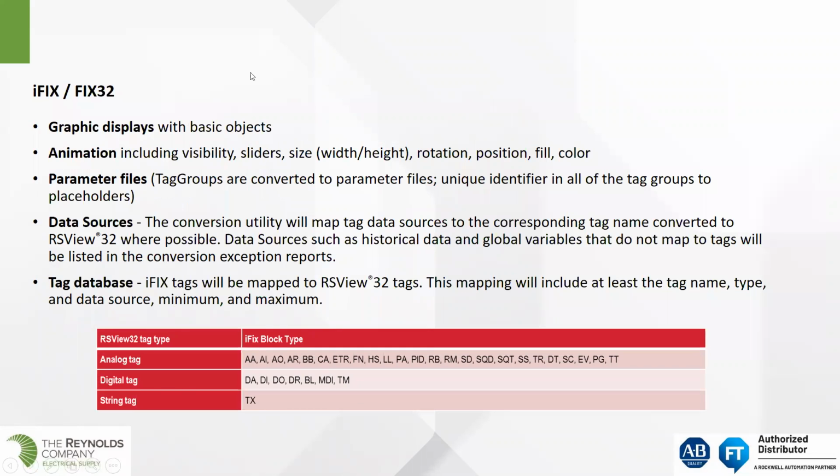Okay, and so the next slide: what will be converted? We'll take this separately between iFIX and InTouch. With iFIX, like I said, iFIX is a little bit more complicated. But as a base, the graphic displays with the basic objects are converted. A lot of times that's really what we're looking for here, so we don't have to recreate a lot of those graphics. So number one, those are converted.